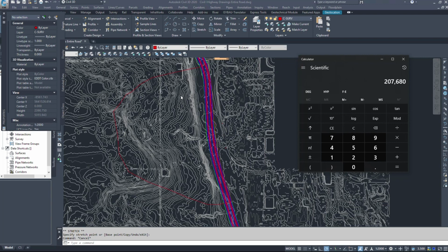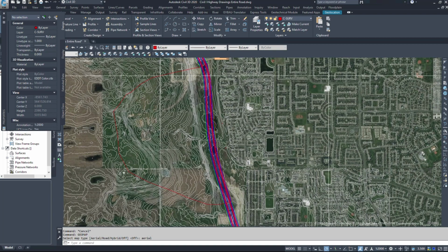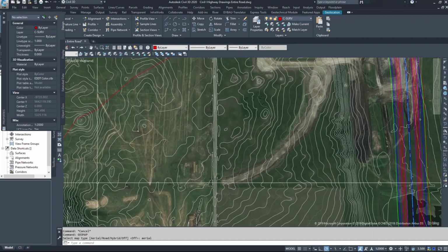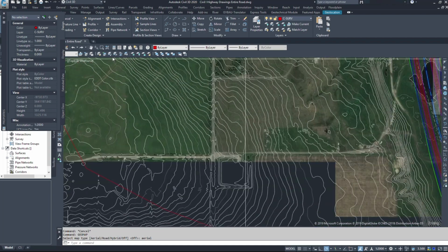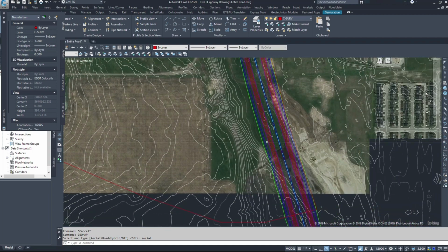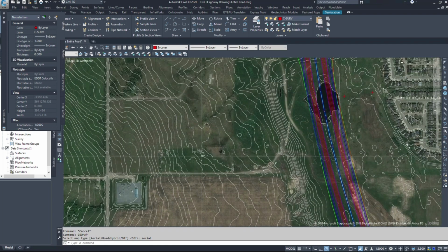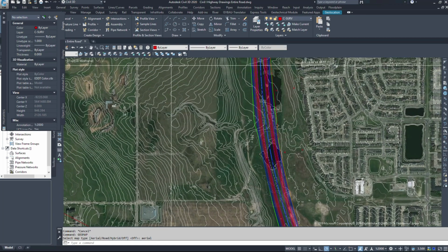clay, compacted clay, etc. So again, we'll just quickly turn the geomap back on just to see what our ground is composed of. Now, just taking a quick look, the majority of this is grassy area, farmers' fields, dirt, areas where there's plants and the vegetation can drink up most of the water. So this helps us when we're designing our pond. Basically, it means we don't need as big of an area for a pond than say if this was all concrete.